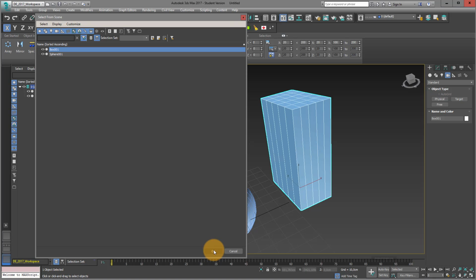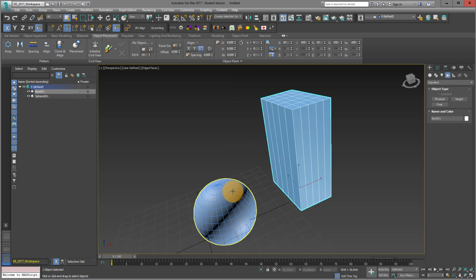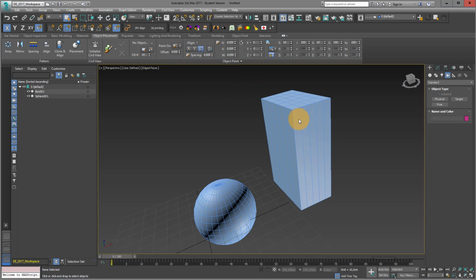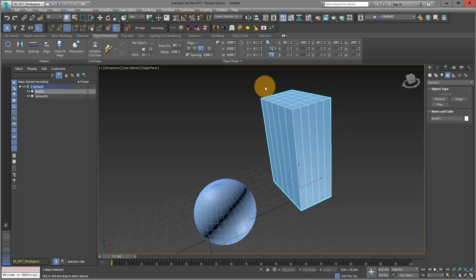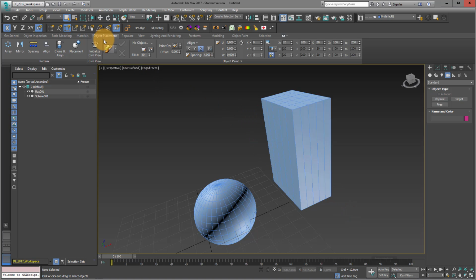You select objects with Select Objects. You can also just say rectangular selection. By the way, if you press down the mouse, always if there's a little bit of an edge here, then there are more options. Then you can see that the different shapes are not really important to me. So if I just choose rectangular select, then you can just select it like this. And here's something like window crossing, which actually doesn't work for my workspace because I changed it to auto crossing like in AutoCAD.